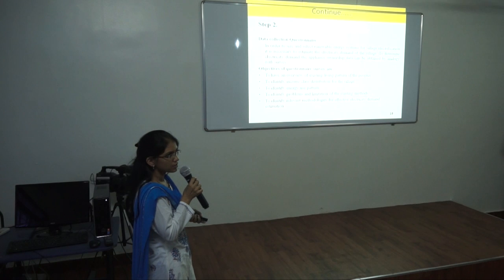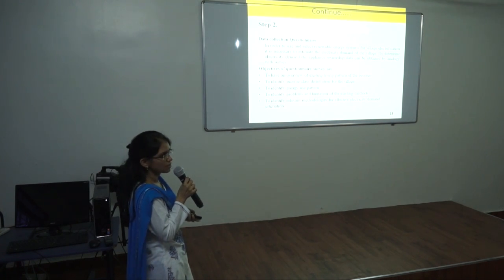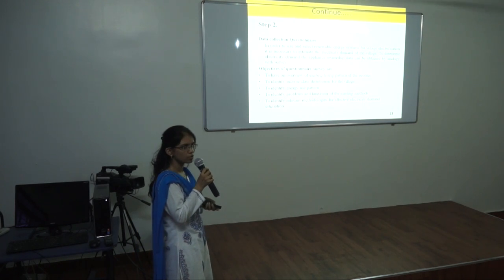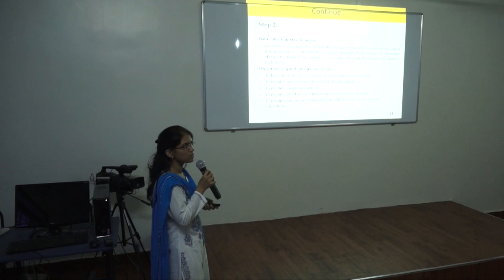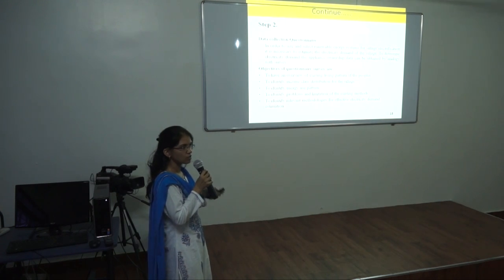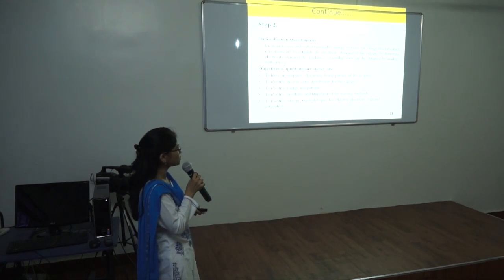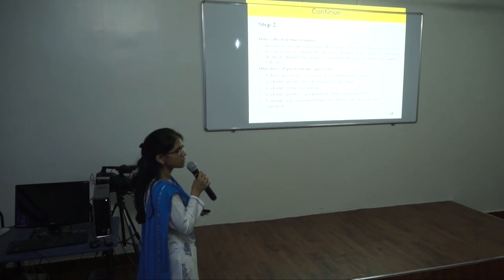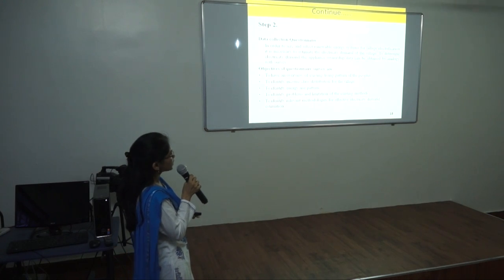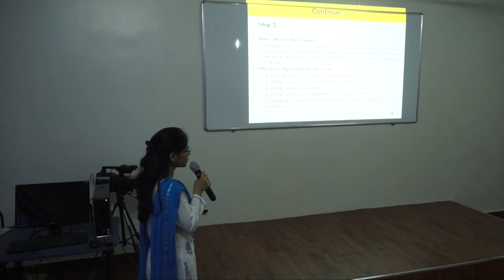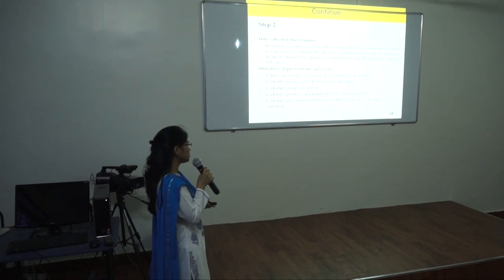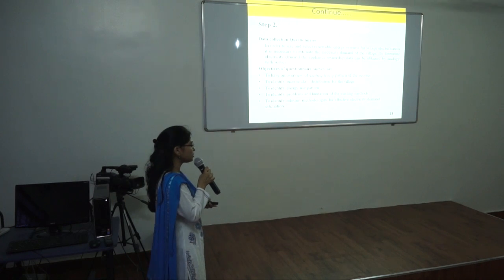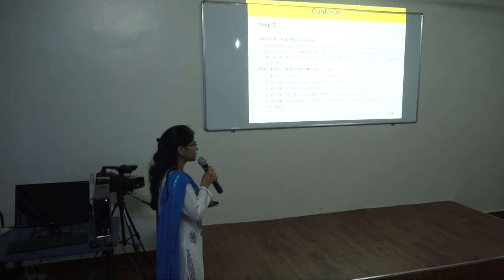After selecting the site, the next step is data collection and data analysis. In order to size and select a hybrid energy system for rural electrification, it is necessary to estimate the electricity demand of that village. For this purpose, data collection questionnaires are given to the villagers. The objectives of the questionnaire survey are to have an overview of the existing living pattern of the people, to identify the income class distribution for the village, to identify the energy use pattern, to identify problems and limitations of the existing methods, and to identify a relevant methodology for effective electricity demand estimation.